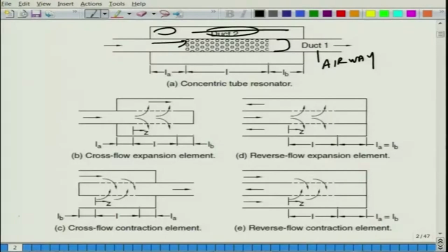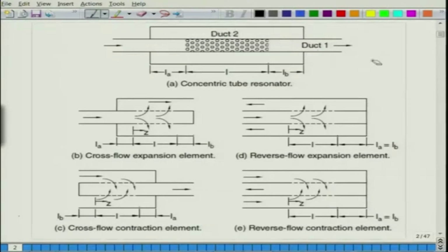But for our cases, to keep our plane wave analysis simple yet reasonably accurate, we will assume, at least for this configuration, 0 mean flow. Let me write it. If you have a Mach number U naught here, uniform velocity, in all these regions we have 0 mean flow, that is U2 is 0 here, but capital U1 is some value here, typically less than 0.15 or so.